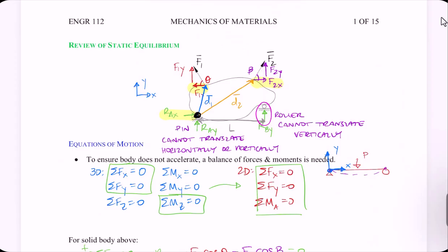When I go to do my other ones, this one, when I do F1x, I'm going to see counterclockwise. When I do Fy1, it's going to be clockwise. So in the direction of my force towards the point, it's to the left of it, so that will be a clockwise moment. So that is what we will see shortly.